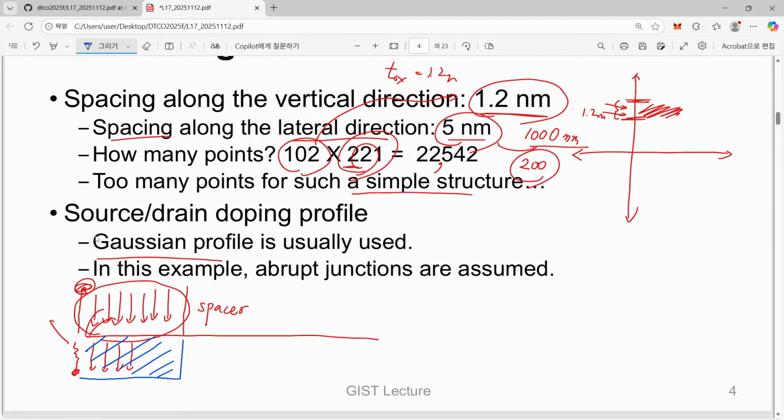Actually, it's not, because when an ion comes into this already existing silicon crystal structure, it experiences a certain sequence of collisions, not just a single collision, but interaction with all of the silicon atoms. So the direction itself is not just unidirectional, it can change.